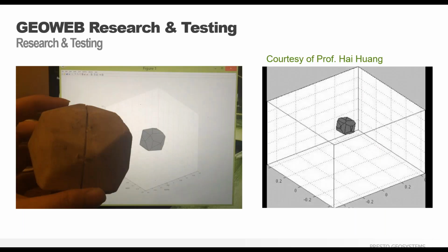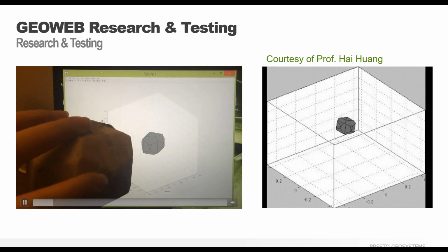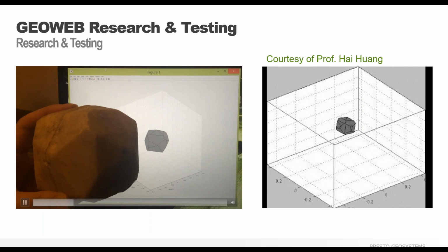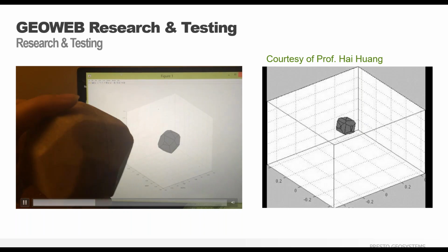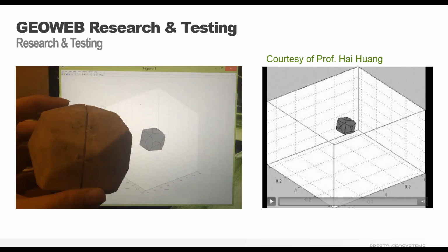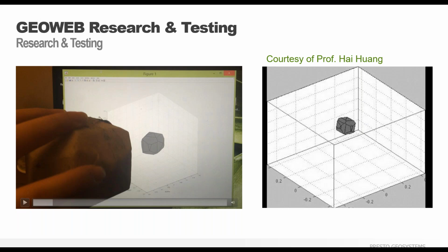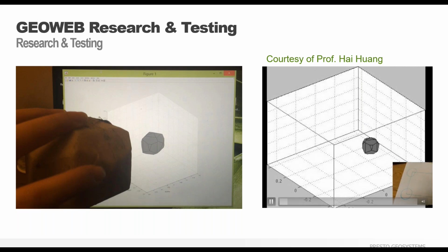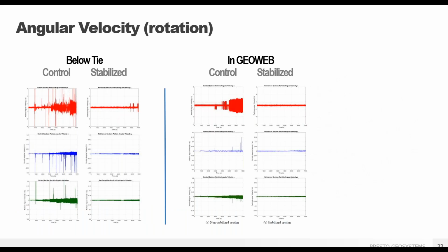So here you can see how the smart rocks measure both the movement and rotation of those panels. You can see here how it measures the rotation of that ballast particle, and also how it measures the movement of it when it's subjected to a train passing over it. So here the slide shows basically the velocity, and that's the rotation, of that particle.